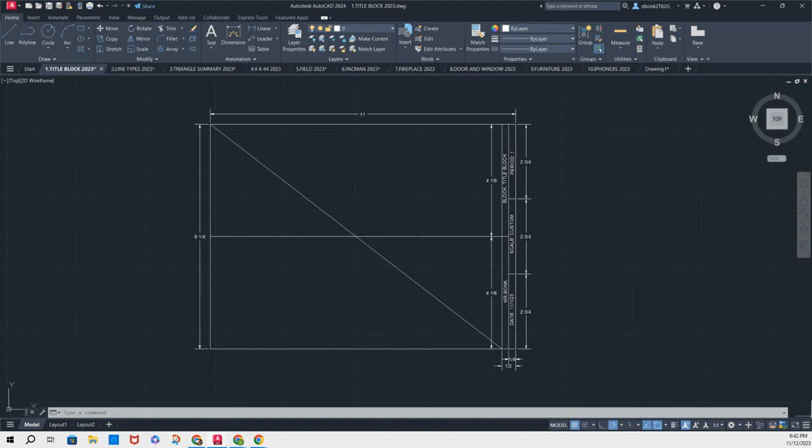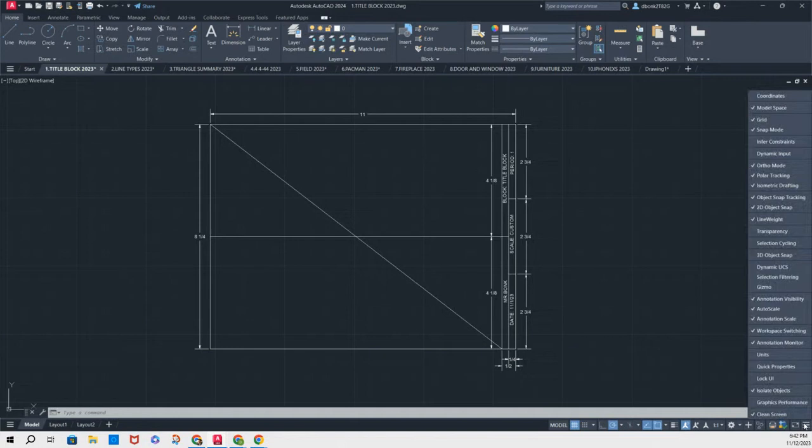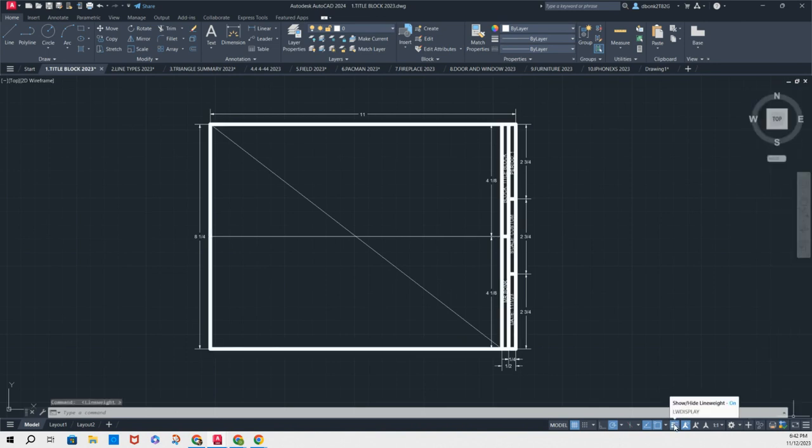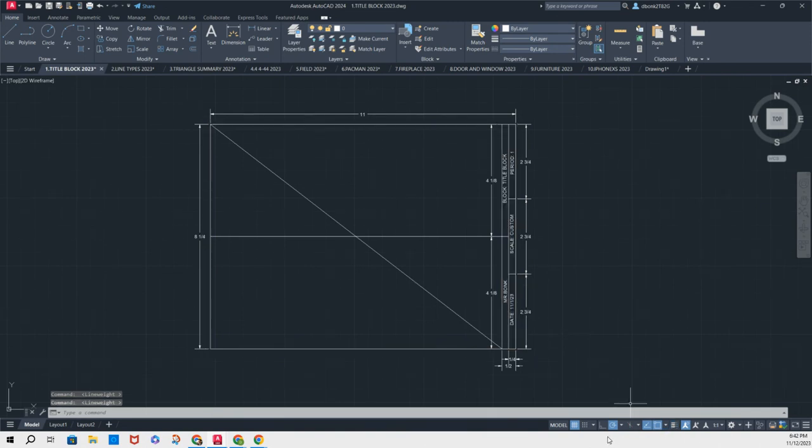One more thing that we turn on, and I'll end up using, is if you click this 3-bar button right here, it brings up a big long menu. Line weight should be checked. The check mark isn't there when you open the program. Check that. And then this button pops up when you do that. That gives you the ability to turn on the visibility of line weights, which you change as you work. So I'm going to turn that off for now so it's not so clumsy looking. But you want all that stuff on.